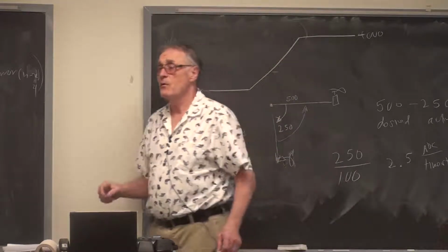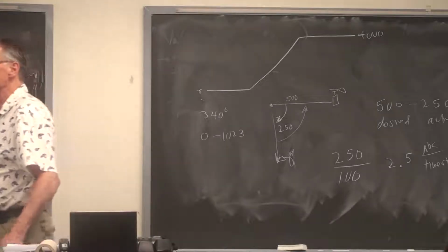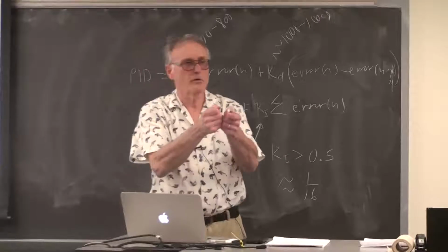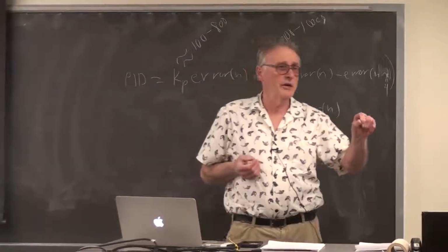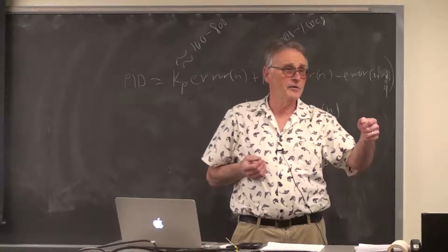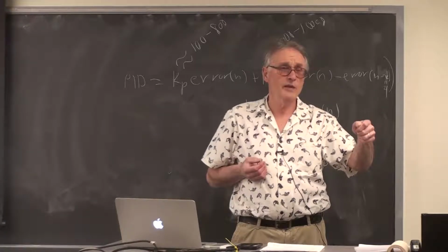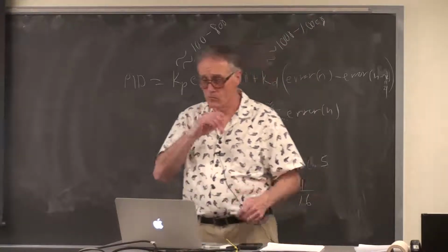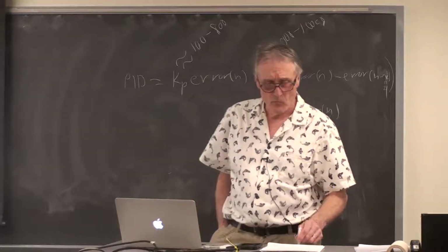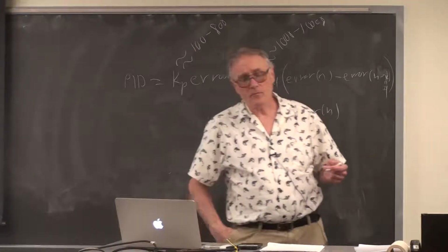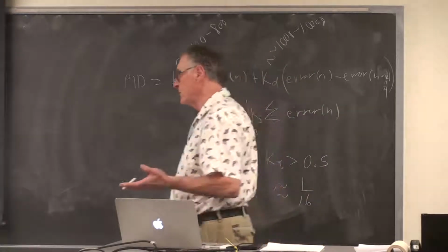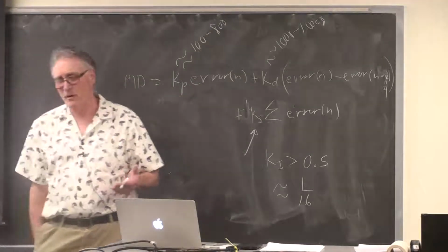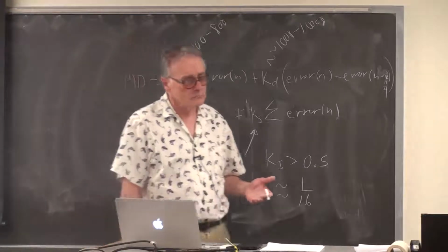And if you wanted to set 50%, instead of measuring the resistance with an ohm meter, you could, of course, hook up the ADC to it and turn it to 512 or 511, and you'd be at half scale. So if you end up using the absolute value of the potentiometer, you'll have to measure it because it's not guaranteed, but it's probably around 8.7 kiloohms.